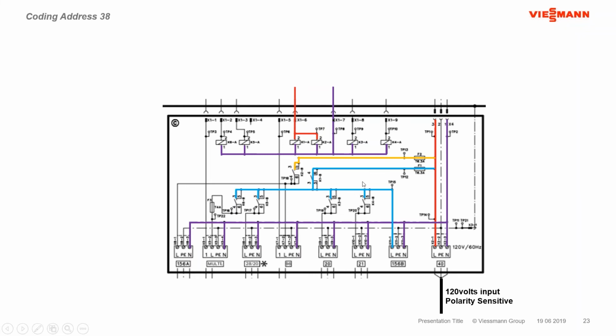We are going to need the K3 relay up here to energize before the 20 output is going to be powered. K4, same thing. We need the K4 relay up here to energize before the domestic pump will get its power. And the 2820 output is attached to, looks like the K5 relay sitting over here for that to operate. So those are basically in a wait state for those relays to close for them to operate.